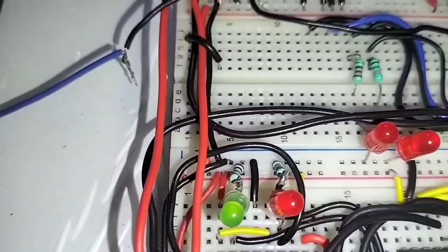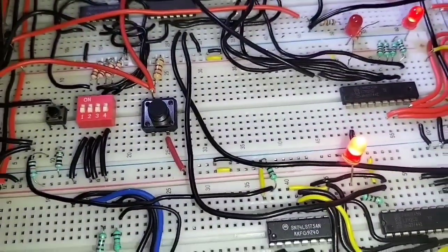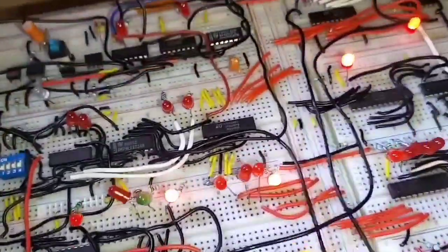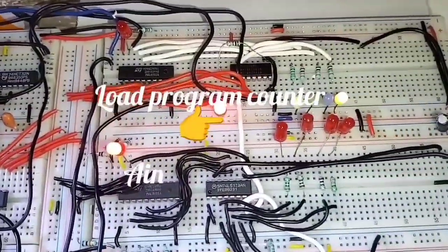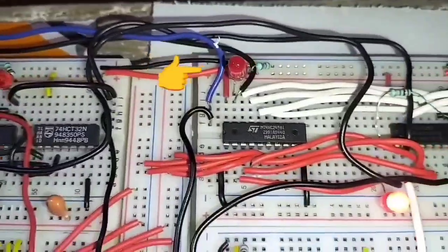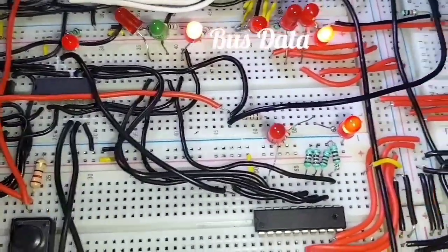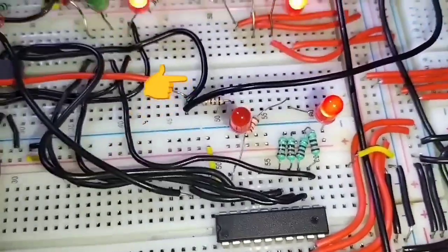Now again the counter out and RAM address in micro instructions are active. Program counter is 1 now. That will be the address of RAM when we give the next clock pulse. Now we can see the data of the RAM, that is the 9, on the bus